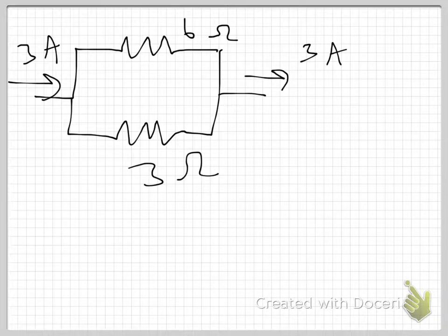It's 6 volts. And this is a parallel configuration, so I know that both resistors see, quote unquote, the 6 volts. This is the voltage drop across both, this is the voltage connected to both resistors, right? So now I can calculate the current.